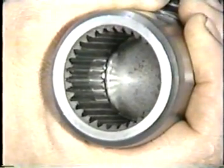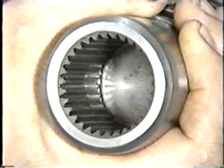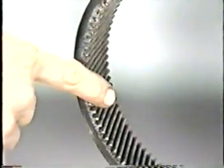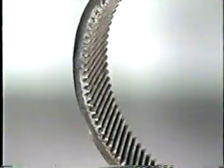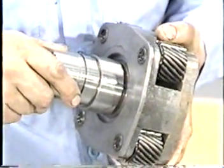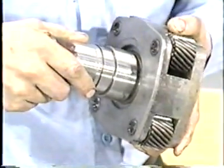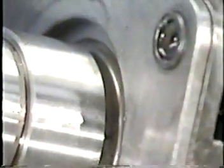To inspect the input shaft and carrier gear assembly, check the input shaft splines for wear or damage. And check the teeth on the ring gear of the carrier assembly. The contact surfaces should be free of chips or nicks. And inspect the thrust washer for wear. Check for end play of the input shaft. The shaft should have less than 60 thousandths of an inch end play in the carrier assembly. If end play is excessive, jump out problems could occur.